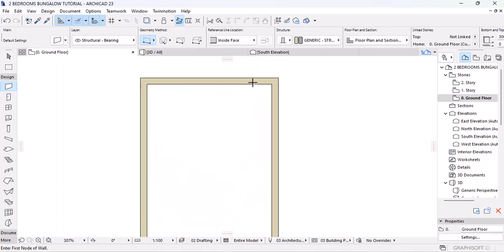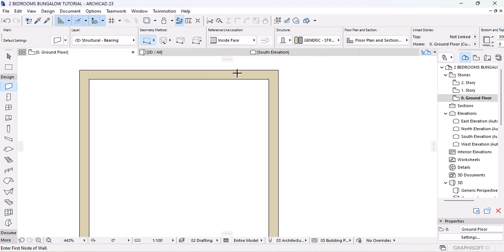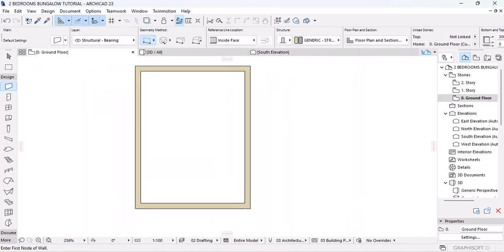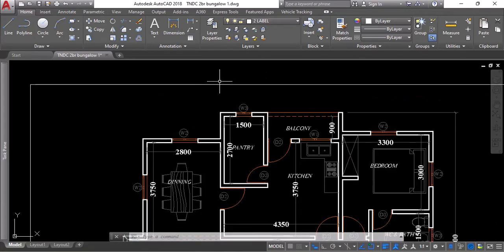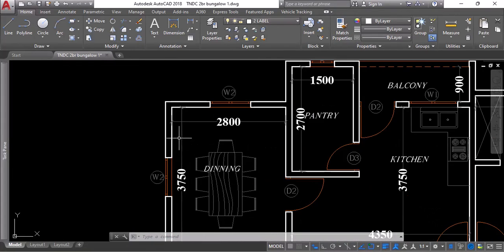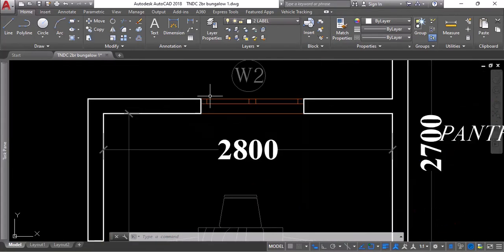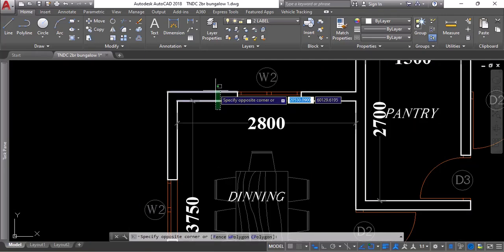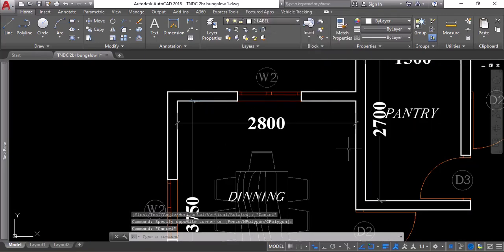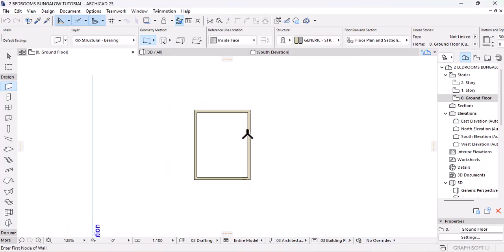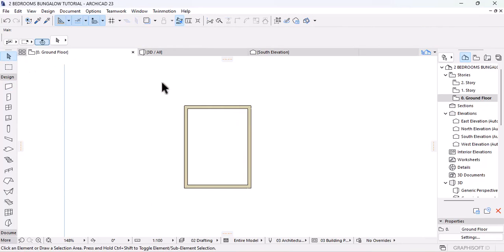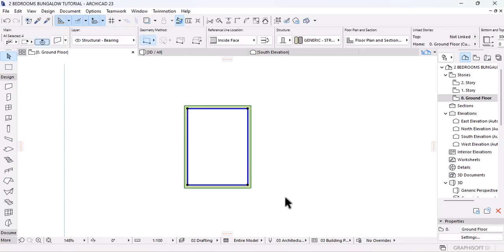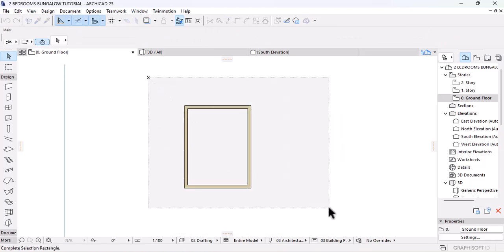While I'm modeling, I don't like my wall to be having colors. Like if you go to this AutoCAD, see the line doesn't have any shading. But if you want to put a wall shading, it's not bad. But I don't like putting shading on my wall. I like it to be a thick line without shading. So what I'm going to do here is I'll come to my AutoCAD. I'll select neutral because I'm going to use this arrow. I'll highlight, just drag over the model and click on your left mouse button.